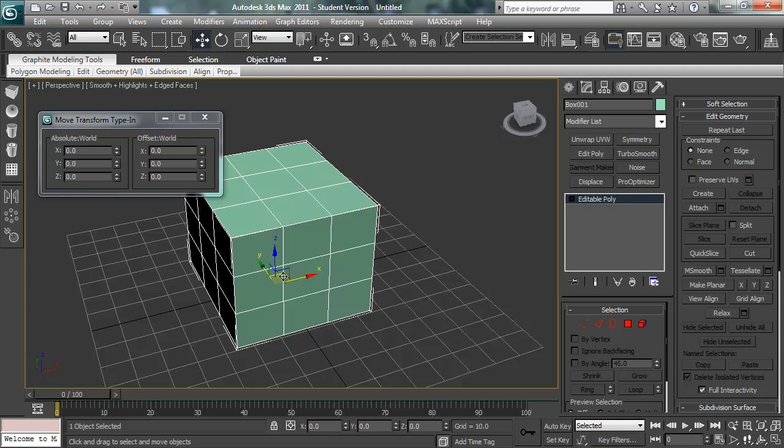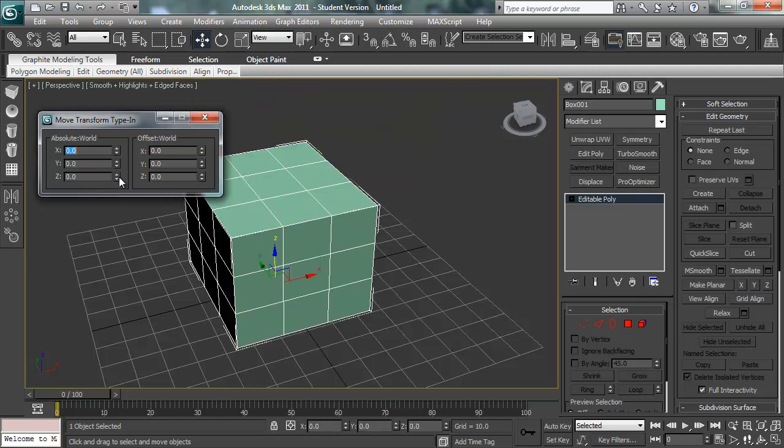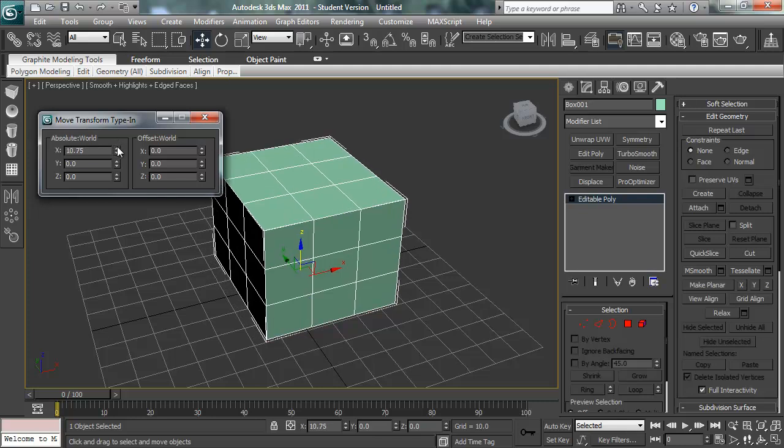Another way to position your object at 0, and this works with all rollers: if you see a roller and you right click on it, you're setting it to the minimum amount, which usually in these cases will be 0. For some things that can't go down to 0, it'll go down to 1 usually. So just right click on the roller and it'll do that. You can also drag a roller, and this transform typing is quite useful for making very precise adjustments if you're finding that movements here are a little bit clunky. So that's kind of useful.